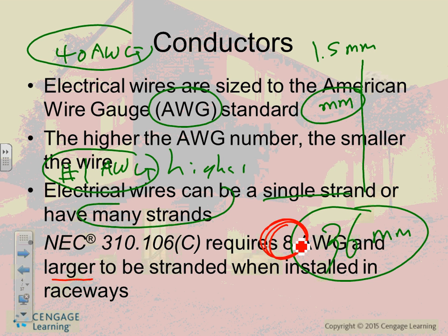So, any comments, guys? Any questions about stranded? So, stranded, solid. If you're doing commercial or industrial, everything is stranded. If you're doing residential, everything is solid, almost. And that's the rule. Stranded, well, sometimes they have one wire, but almost all of them.